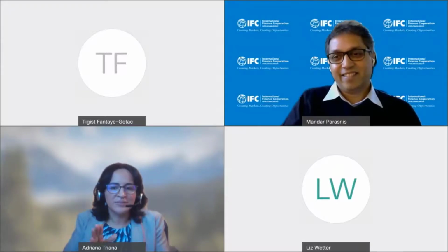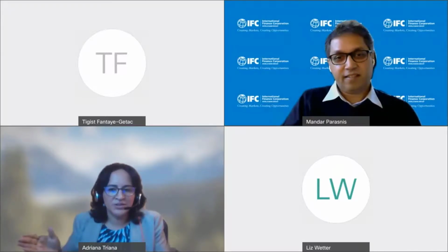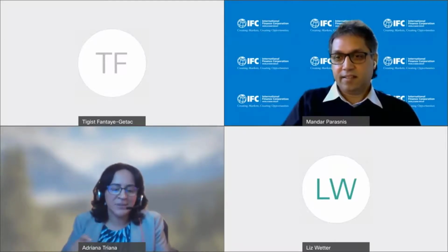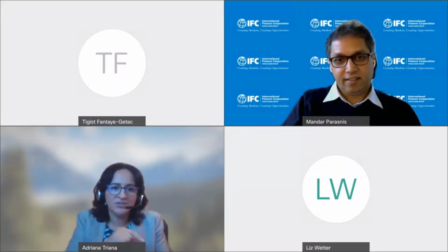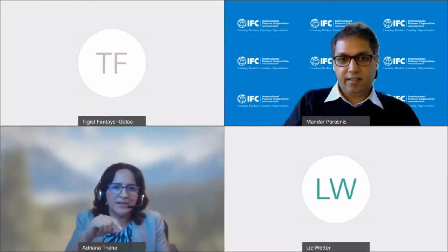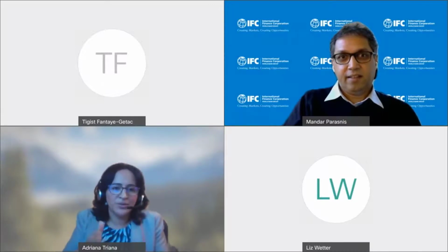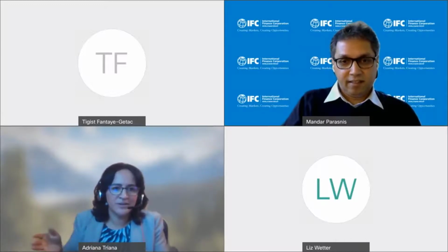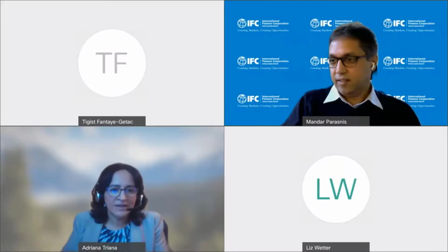So it's just that PS3 refers to good international industry practice. One of those is the EHS guidelines. The discrepancy that happens sometimes is between the local legislation and the EHS guidelines parameters or the good practice guidance. And in that case, the requirement is to apply the more stringent one. So you compare the two of them, and one says the effluent emissions are at 30 milligrams per liter, and the other one says 50. So the more stringent one is the one that will be applicable.